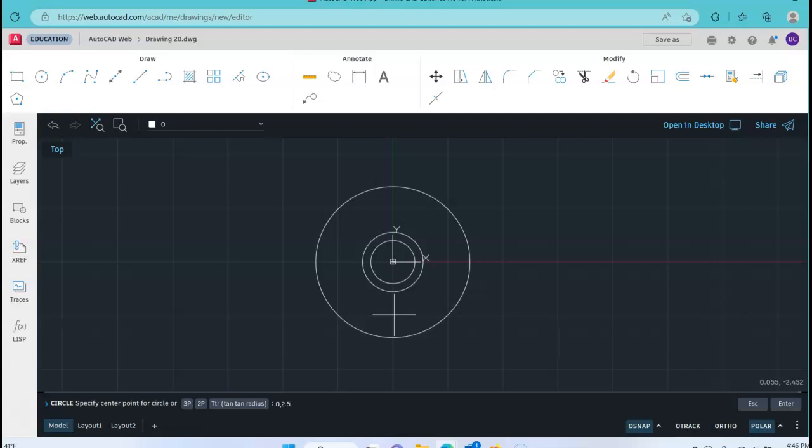So my y here will be 2.5, not 2.5. It will actually be, let me cancel that out. It'll actually be minus 2.5 because we're going down and it's down here. So click enter. There you go. And now I can decide that's also a 1-inch diameter here. So I'm going to type in D, 1 inch, and hit enter for that position.